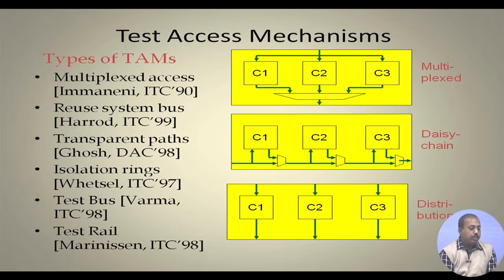So the power consumed by that core will only come into the picture. If the maximum power consumed by any core is say P, then the maximum power consumption of the entire test session is given by P. However, since the test is prolonged over a long time, the test time may be quite high, and that will cause the testing cost to go high as well.